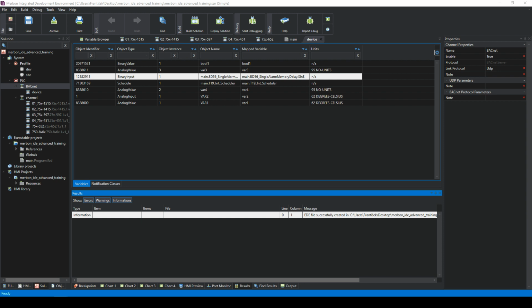If you mean in general, we don't have security in BACnet. There is some new standard already existing, but I think no companies right now are implementing it because it's very performance inefficient. So it's very hard to use it.